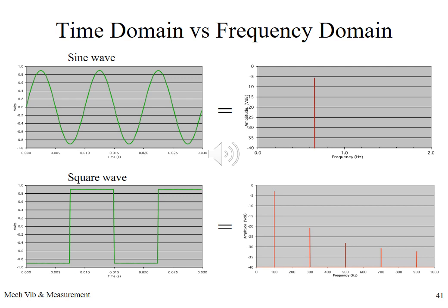Alternatively, a square wave is essentially a summation of odd integer harmonics of sine waves. So we have a sine wave with a frequency of f added to another sine wave with a frequency of 3f and 5f and 7f and so on. And if we do that enough times, we will have a square wave as a result. And you can see that immediately in the frequency spectrum, where we have a peak at 100 Hz, the fundamental frequency, a smaller peak at 300 Hz, 500, 700, 900, and so on as we increase up the frequency spectrum.